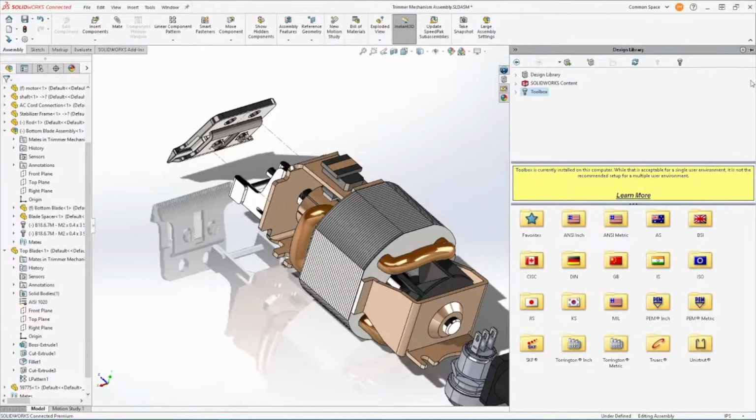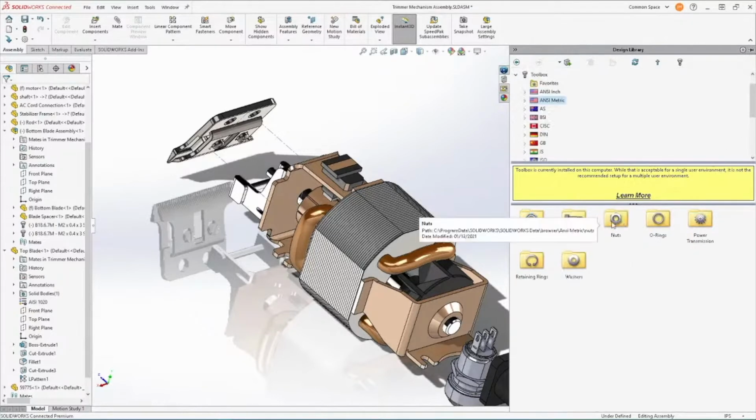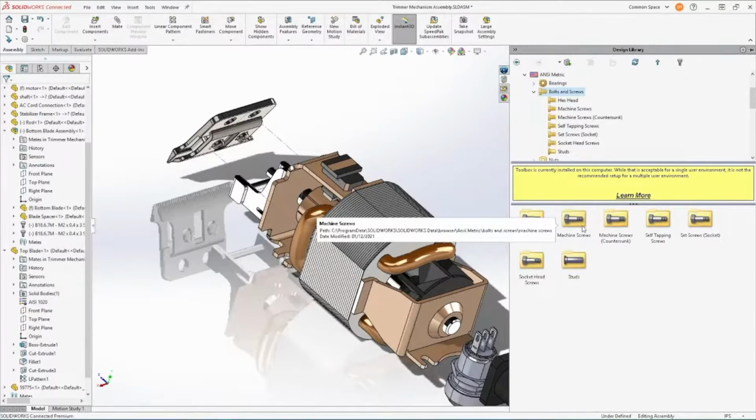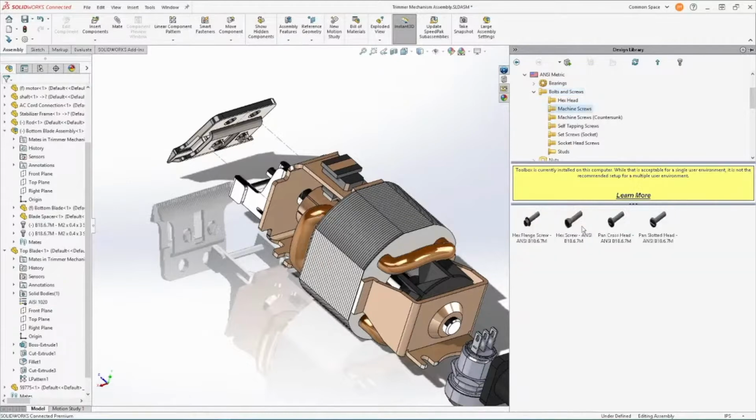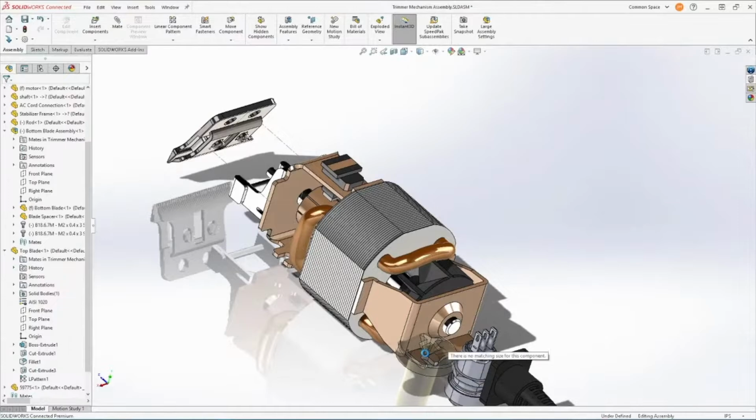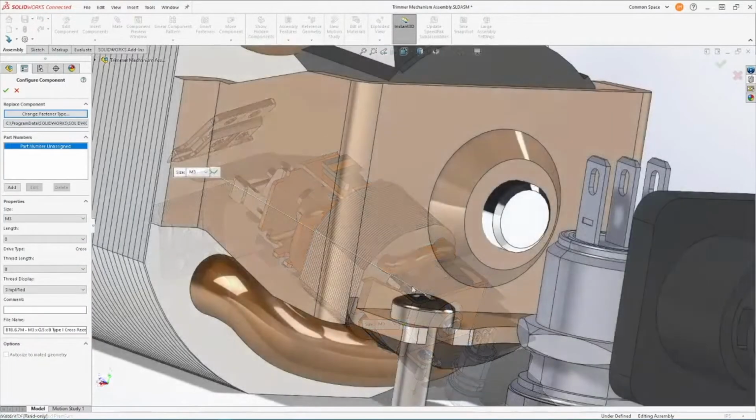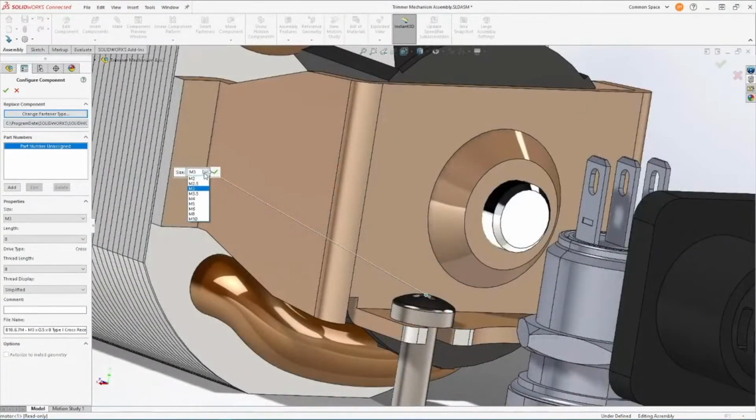All right, so we're going to need to constrain this motor enclosure with some screws. For all of you SOLIDWORKS users, you're very familiar with Toolbox, but it's now in 3DEXPERIENCE SOLIDWORKS. For those of you who don't know, it's basically like having an entire machinist library right at the palm of your fingertips. You can see as I drag and drop a screw in there, it's automatically going to resize to fit the hole that I need, which saves time for modeling and mating standard components. And as I said before, it is the latest functionality as of this latest release.